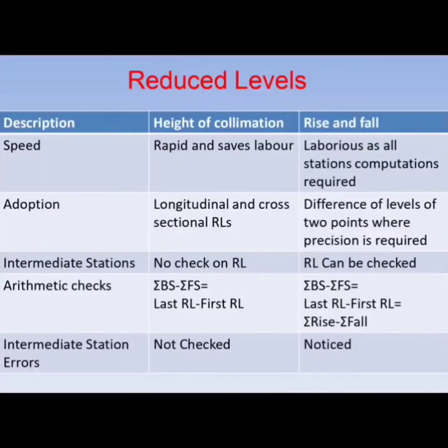Residual levels can be calculated through the height of collimation method or the rise and fall method. In the height of collimation method, computation can be rapid and saves labor. In the rise and fall method, calculations are laborious as all station computations are required.